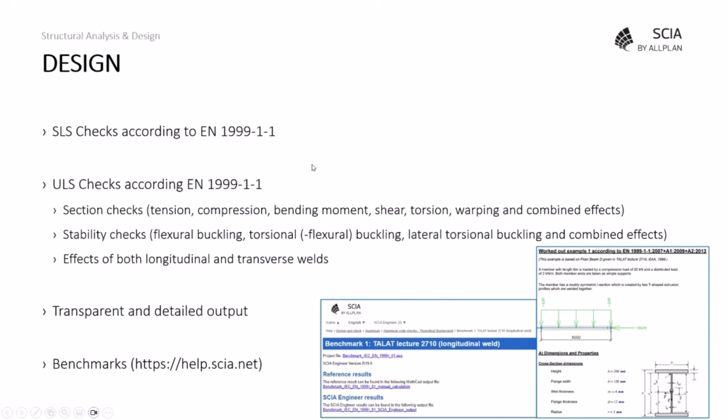When you obtain the deformations and internal forces after the finite element analysis of the full model, you can perform the necessary checks. Due to the lower elastic modulus, often the SLS design is decisive. In SCIA Engineer, you can define the deflection limits in the aluminium settings or in the buckling settings of the 1D members, and these limits can be compared with the relative deformations of the structure.